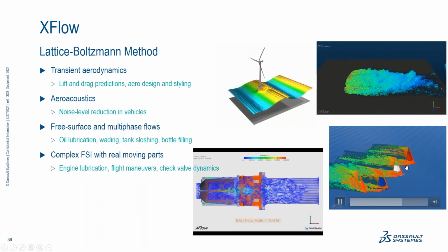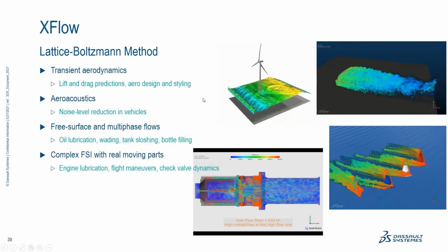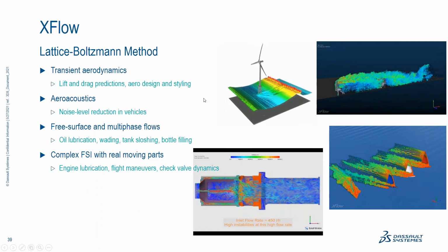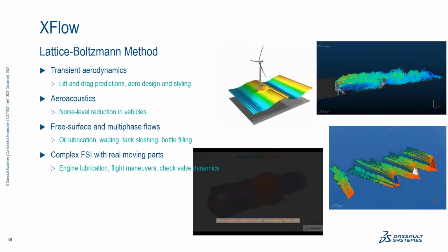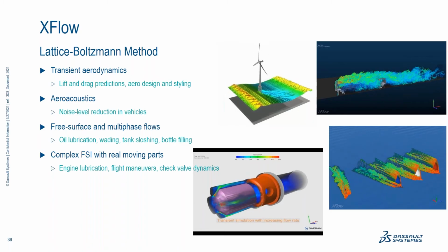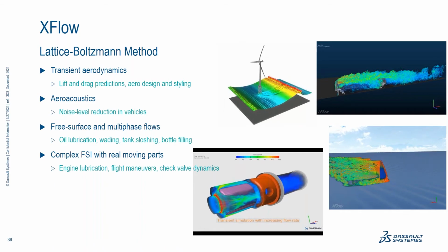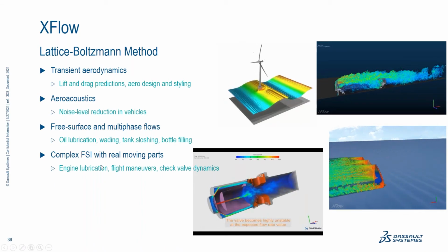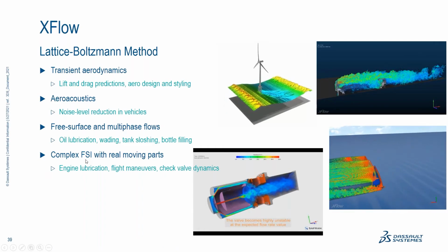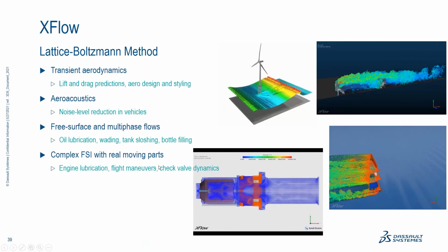These ones here, again, you see, highly turbulent problems, highly transient problems that, obviously, a steady state solution is not going to be good for. That is something that XFlow, with that methodology, Lattice Boltzmann, is much better suited for. Also, another area is fluid solid interaction, FSI, with really moving parts.